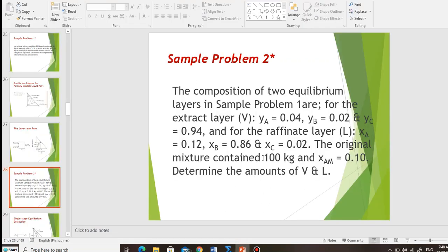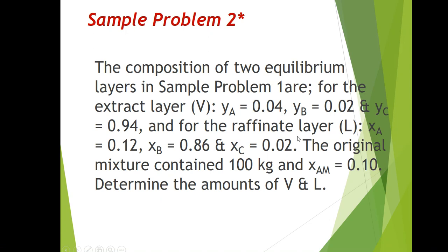Okay. However, class, you cannot answer this sample problem unless you have already done the graphical trial and error procedure illustrated in sample problem number 1. So it's important that you know how to determine the composition of the extract and raffinate layers graphically by trial and error before you use it together with the material balance equation in determining the amounts of V and L.